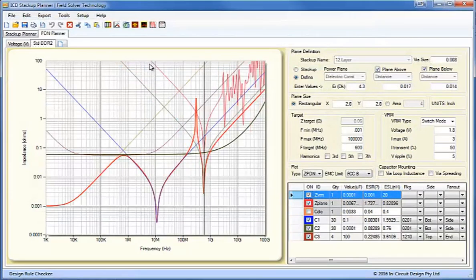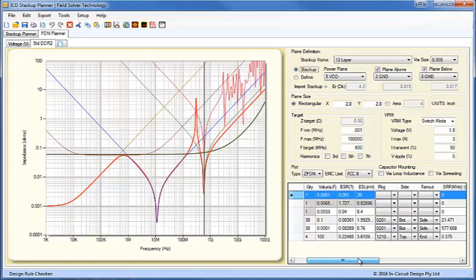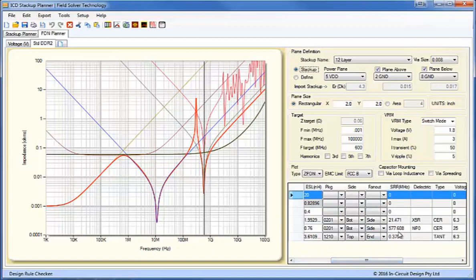Now, years ago, we were told that if we added a 100 nanofarad capacitor and a 100 picofarad capacitor to every power pin on the main chips, it would be sufficient to handle the PDN. We also throw in a few tantalum capacitors, which drop the lower end of the impedance down. And you can see that if we look at the 100 picofarad capacitor in particular, its resonant frequency is around 600 megahertz, and that happens to be our clock frequency, 600 megahertz.